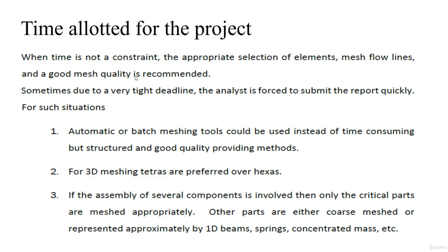If you are going to use hexas, the solution time will be more. So that is why, if you want to reduce the time of the project and you need not have a lot of concern over accuracy, you can go for the tetras. And there are a lot of other factors included in this time allotted for the project. So based upon all of these factors, you need to decide what type of element you are going to use, what type of settings you are going to use, and how you are going to generate the mesh, manually or automatically, and there are many other factors you can select.